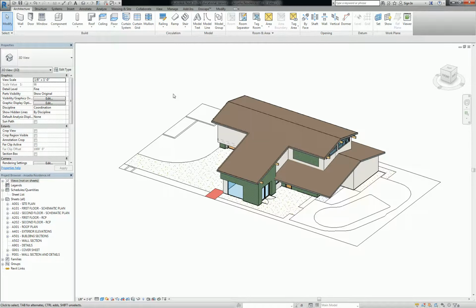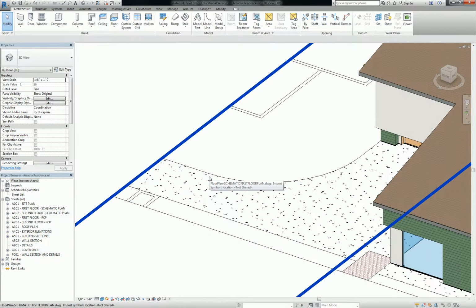So something like the driveway, you generally want to set the grade elevations of your driveway before you set the grade elevations of your grass that's going to go next to it, right? Because in theory, grass is always rising and falling depending on the ecological cycle and stuff like that. So it's never a perfect science there. The things that are perfect and permanent are the ones that you want to set as your baseline.